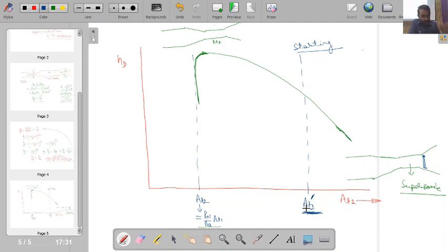Okay, so that is the reason. So now if you see, our operation point is somewhere over here. So normally diffusers which have a fixed area of the second throat operate at an efficiency lower than the highest possible efficiency of the diffuser. Okay, so this is one operational challenge.